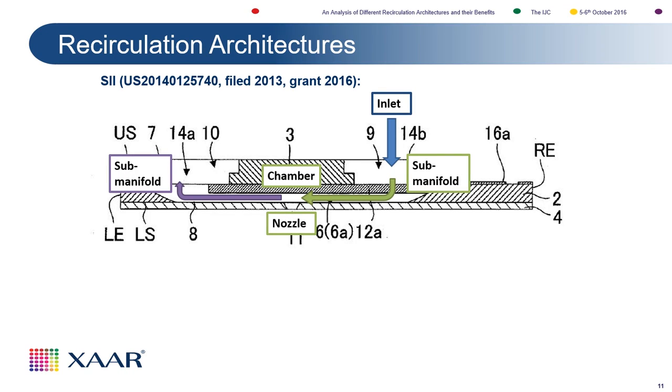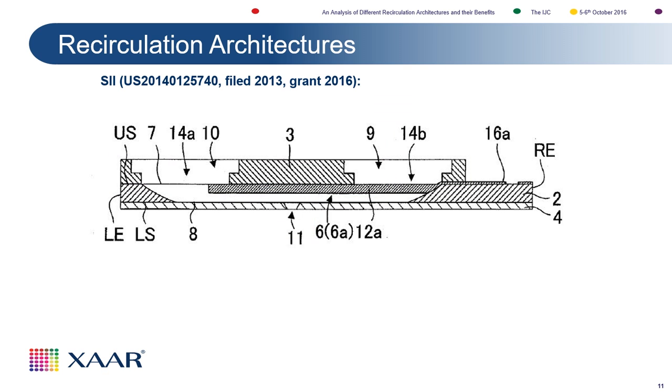You have a flow inlet and then the outlet, but also again the nozzle is in the center, and you can get what we call a double-ended actuation. So you can get actuation from both downstream and upstream focused on the nozzle. So you can get pressure pulses going both to the nozzle, so it's not lost to the outside. You can see with this printer quite a long channel, but it is quite an open structure.